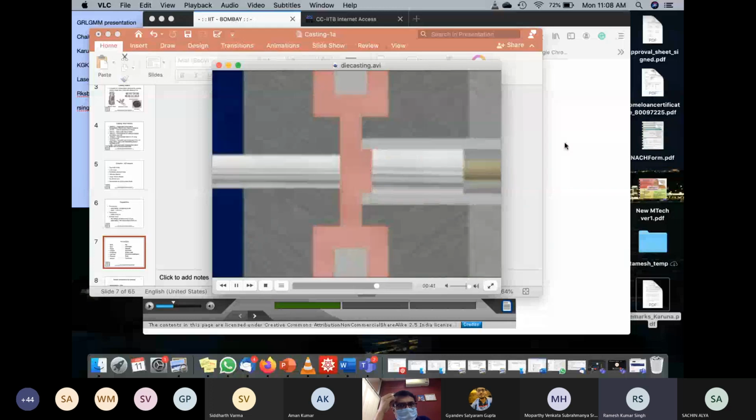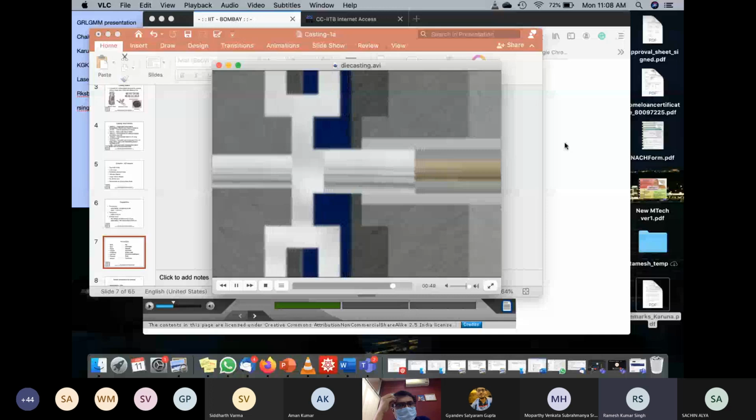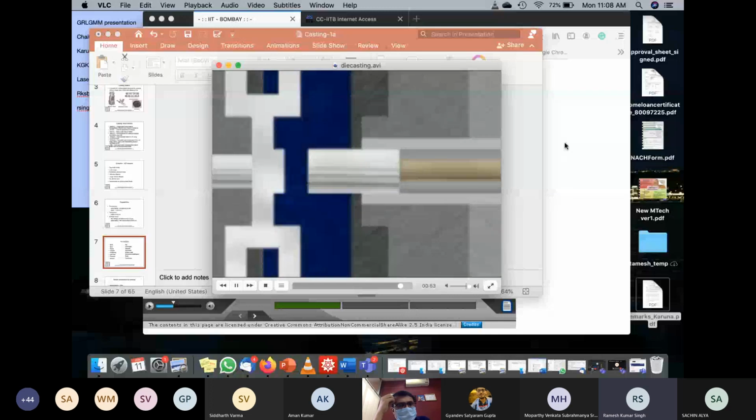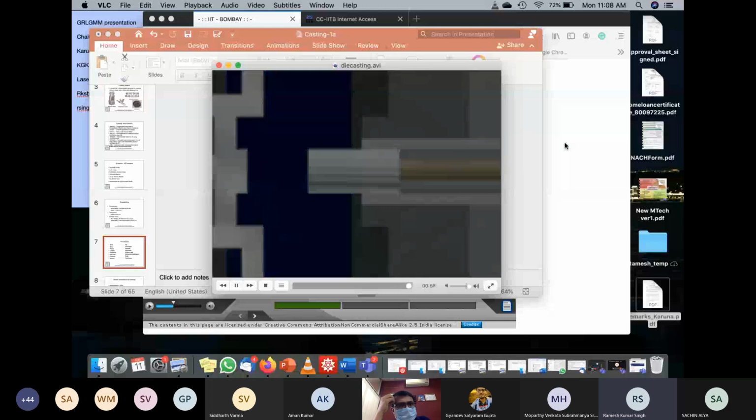After the metal in the die solidifies and the die halves are separating, the plunger thrusts forward, extending the plunger tip past the cover die. This pushes the biscuit that solidifies at the end of the shot sleeve, assisting casting release.